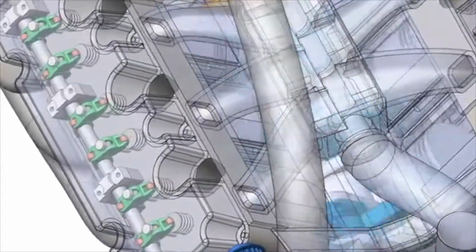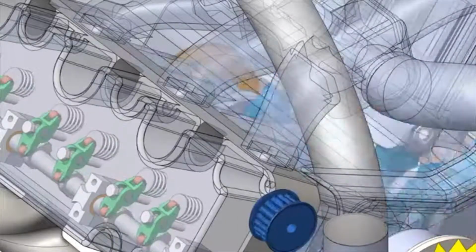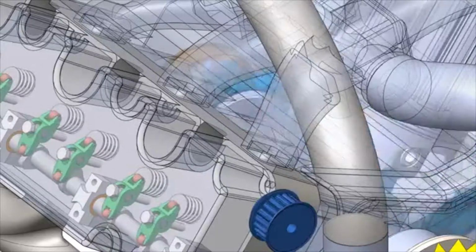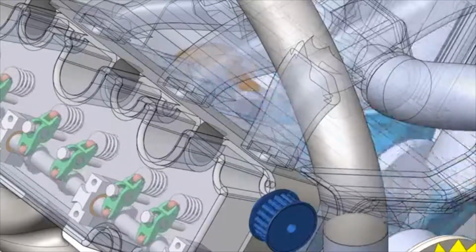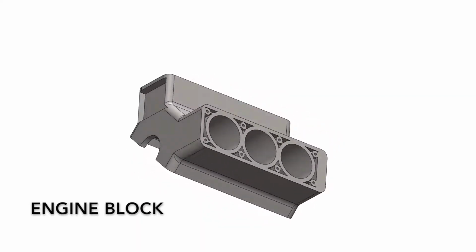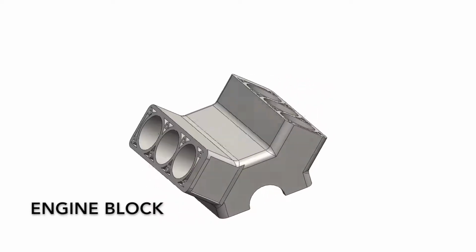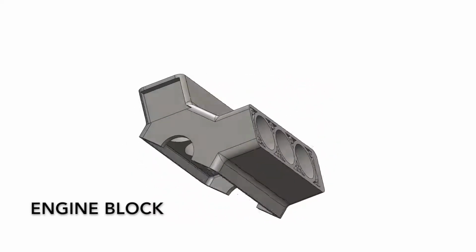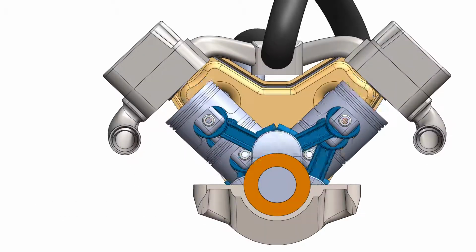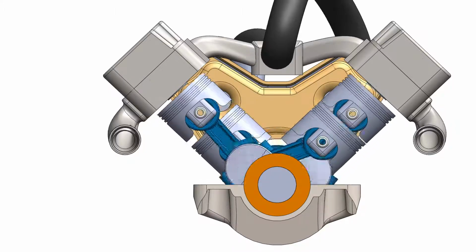By stating that any SolidWorks part or component utilizes standard CAD operations, this can be interpreted as I only use the basic SolidWorks operations such as sketches, lofts, extrusions, etc. for that part. The main body of the engine is the engine block, which houses the cylinder assemblies. Standard CAD operations were utilized for this part, as well as the rib function, which adds a thin wall support along a sketch.